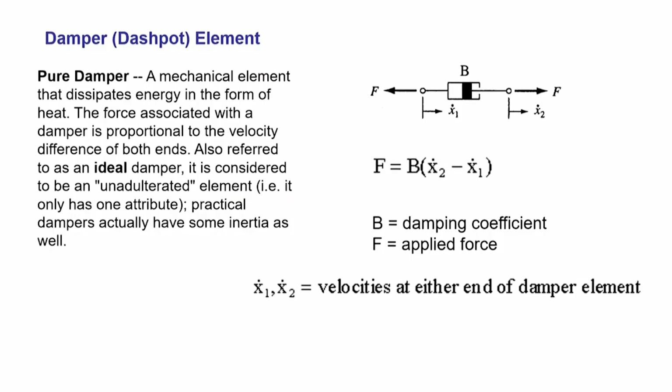Now, just like the springs, we can also have dashpots. Why do we need a dashpot? Well, because if there is a relative velocity between the two ends, I may want this relative velocity to be controlled, so that it does not come like a shock load on the other adjoining systems. So, what this dashpot does is that if suddenly a force is coming at a very high rate from one side, it moves this entire system much more slowly, so that the load is transferred, but at a much slower rate. So that ultimately the energy gets dissipated inside the damper itself.